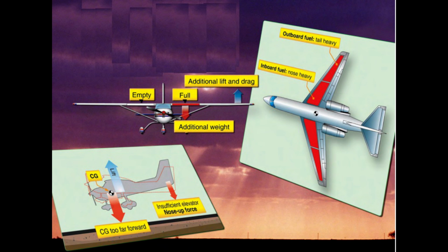2. The manufacturer provides the aircraft operator with the empty weight of the aircraft and the location of its empty weight center of gravity, EWCG, at the time the certified aircraft leaves the factory. Amateur-built aircraft must have this information determined and available at the time of certification. 3. The FAA-certificated mechanic or repairman who maintains the aircraft keeps the weight and balance records current, recording any changes that have been made because of repairs or alterations.